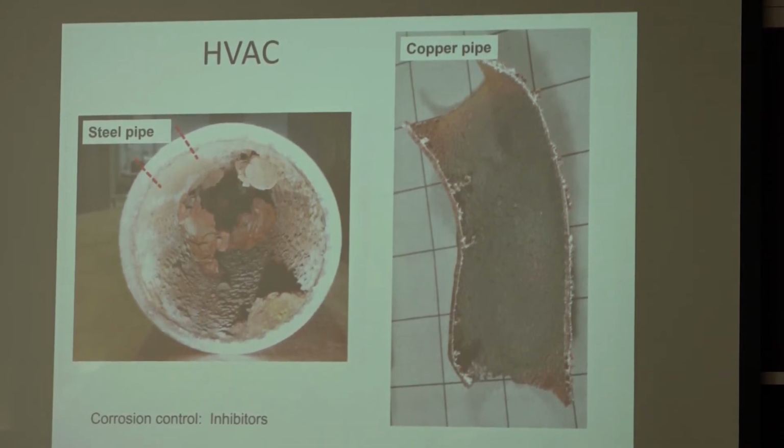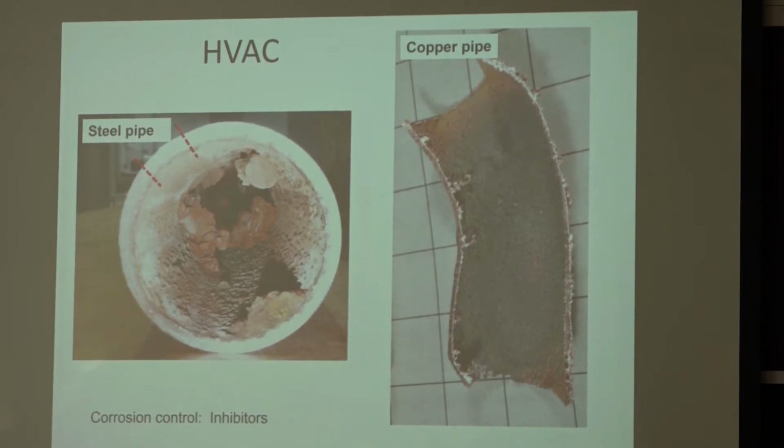Or is it chemical as well? So as far as the erosion in this case, there are always some solids on the surface. So when we call it erosion, there is some interaction with particles. This was a cooling system that went underground, so there was a well. And even though they had filters, there's always some particles involved there. So think about that the particles are going to come and scratch your protective film. And if they do it at a rate faster than you can regenerate it, then that's really where you have a problem.